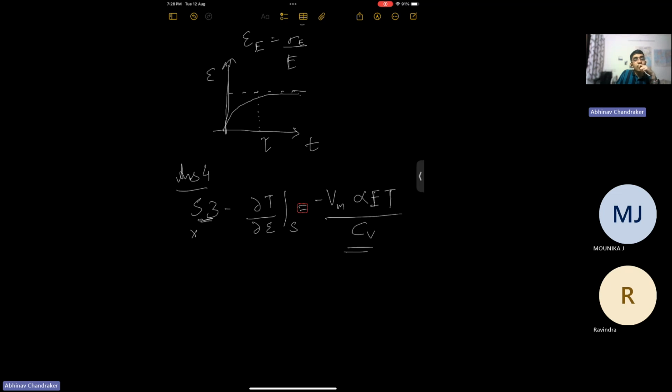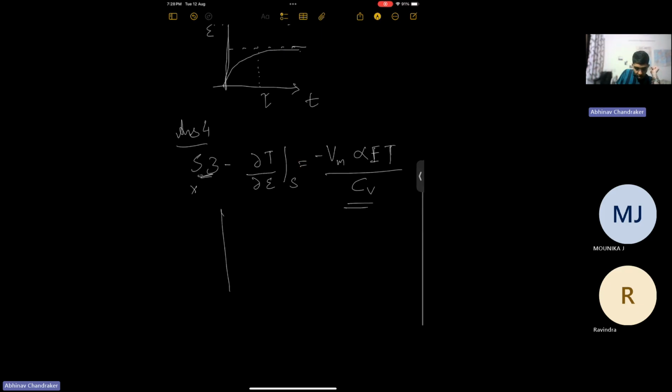S4: a material with a higher sublimation temperature has a bigger dip in the Lennard-Jones curve. So the Lennard-Jones curve is basically the energy well, and a deeper curve will mean that the bond energy is larger for the material. So the energy required to cause sublimation, that is, to break the bonds so that the material converts from a solid to a gas, will be equal to the energy that has to be supplied to take the atoms to infinity.